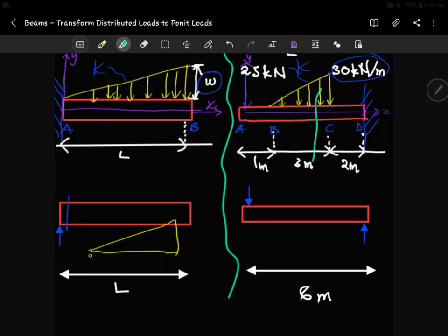We assume that the coordinate system starts here, right? And then in order to get to the center, if I do something of this sort about here, you see that the area here is smaller than the area here. We are just assuming, right? So if you want to move to the center from this position, you have to go more of the length. The actual value there is about 2/3 L. So from here to here I have to move about 2/3 L to get to the center, right?